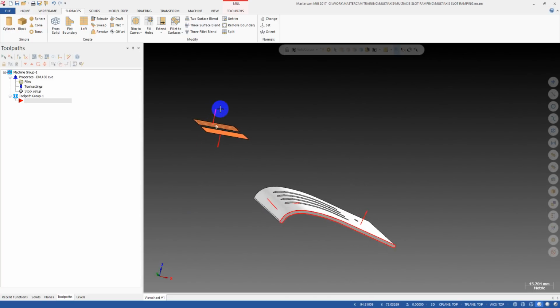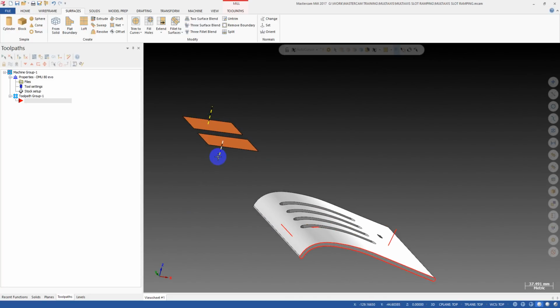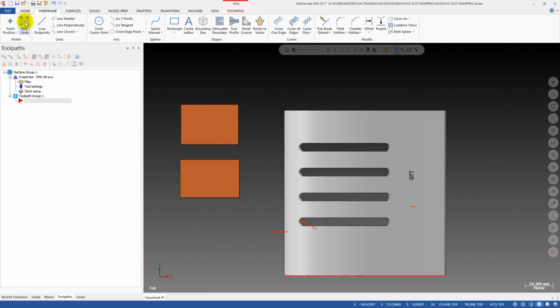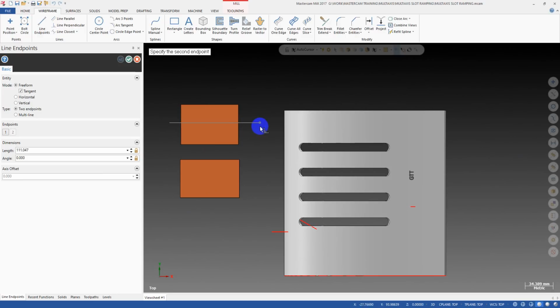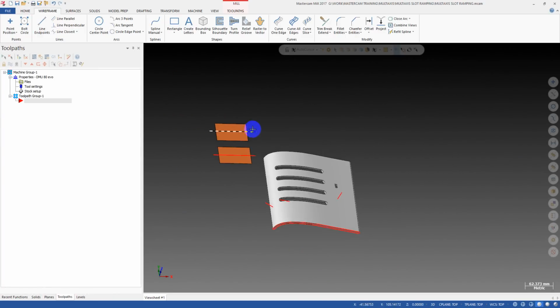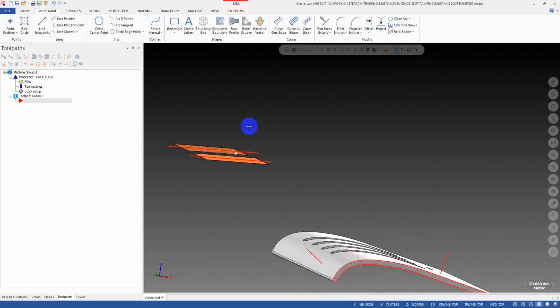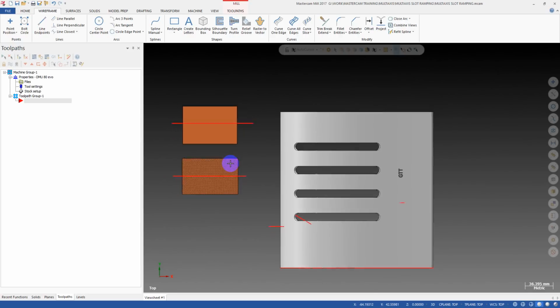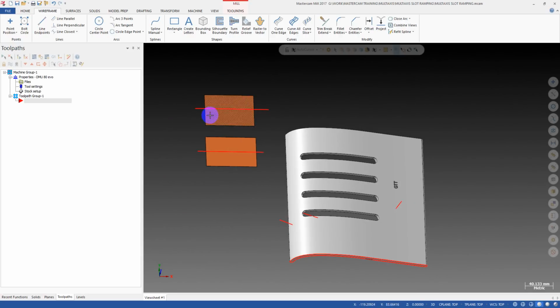So why do I talk with you about the normal vector? Because in multi-axis it is quite important. The normal vector of a surface will define the tool axis direction. Okay, let's see. I have an example, very simple.